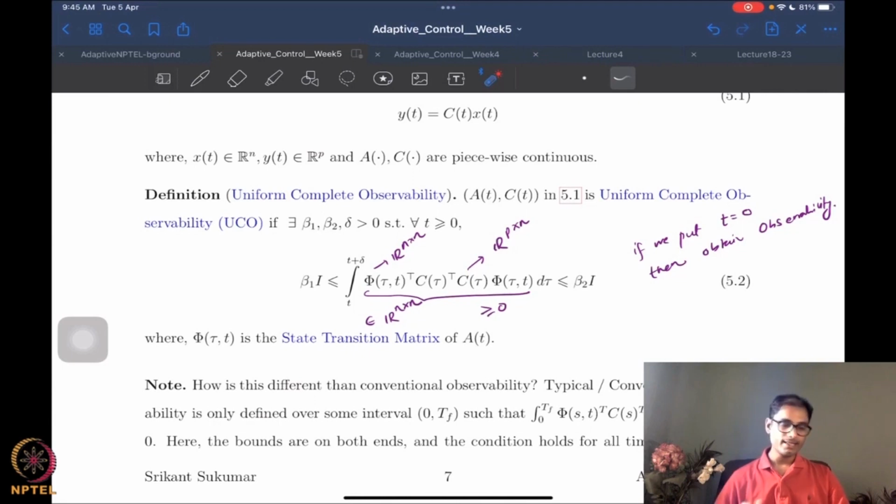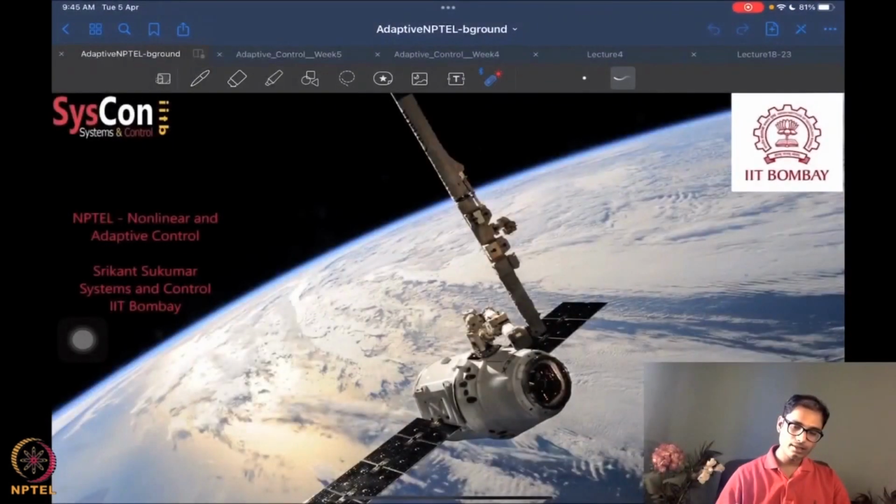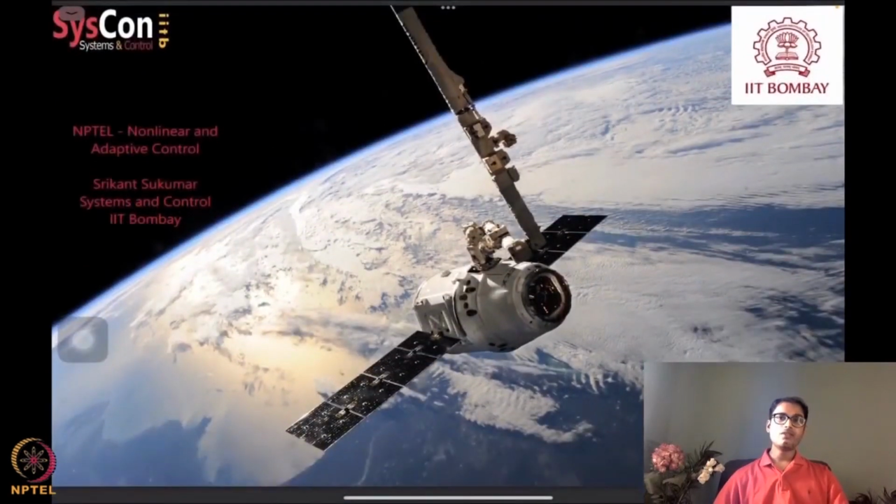All right, excellent. So let's summarize what we did today. We looked at alternate exponential stability. First of all, we made a connection between stability of a scalar system and persistence of excitation. Then in order to extend this notion to vector systems, we looked at different tools. The first was an alternate exponential stability theorem, which seems to be a very interesting alternative to Barbalat's and LaSalle's invariance.